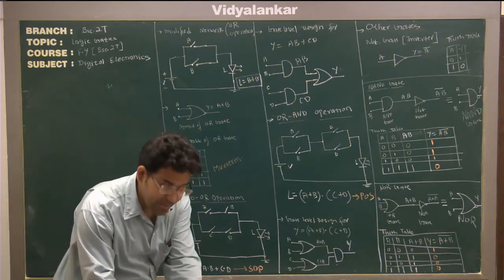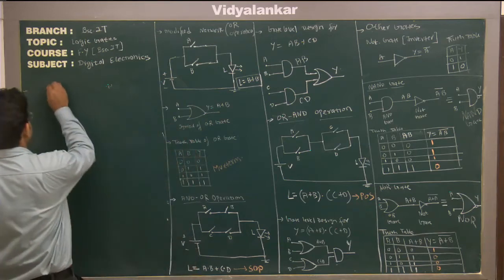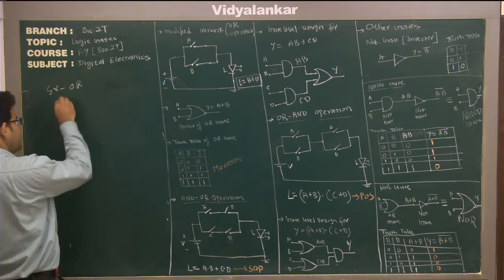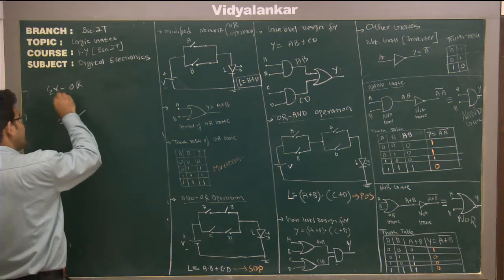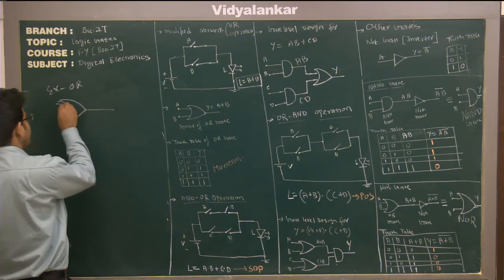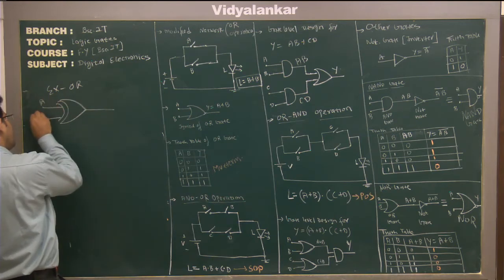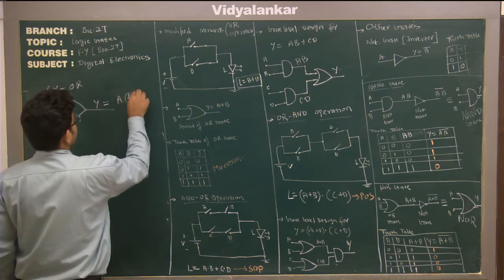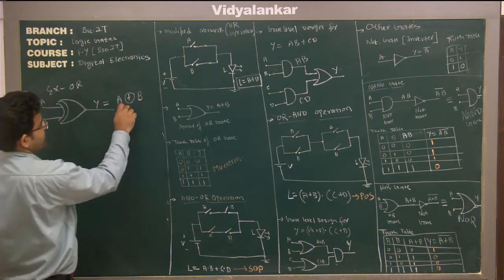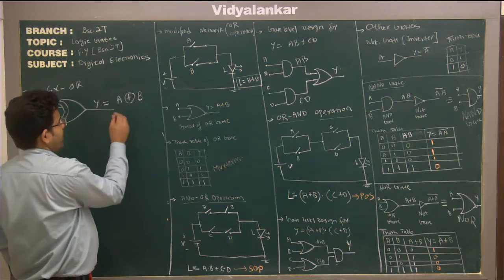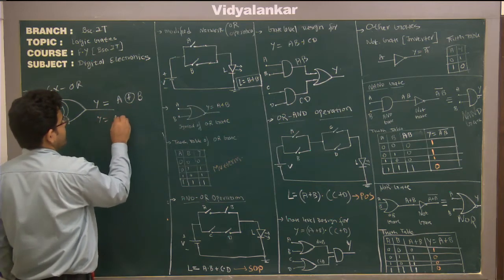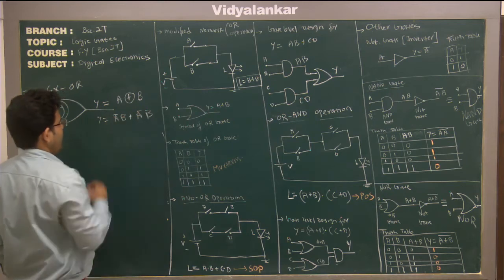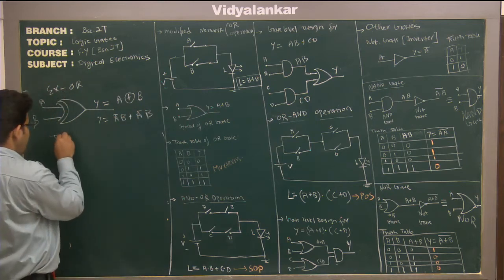So first in that is XOR gate, exclusive OR. So exclusive OR is like this. 2 inputs again and 1 output Y, and XOR is represented like this. This symbol indicates XOR. Actual expression for this is A bar B plus A B bar. Let's see the truth table.